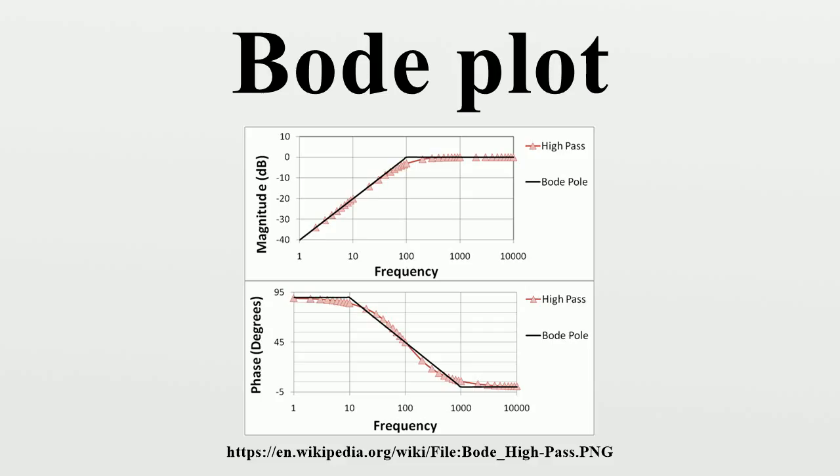The magnitude and the phase of the transfer function are related. For minimum phase systems, there is a unique relationship between the magnitude and the phase, the Bode gain-phase relationship. If the transfer function is a rational function with real poles and zeros, then the Bode plot can be approximated with straight lines. These asymptotic approximations are called straight-line Bode plots or uncorrected Bode plots, and are useful because they can be drawn by hand, following a few simple rules.